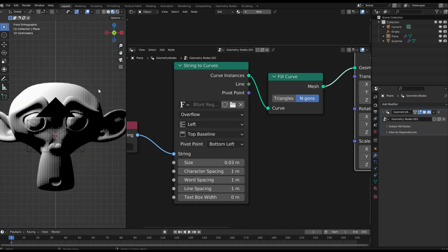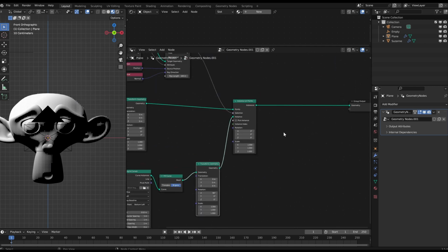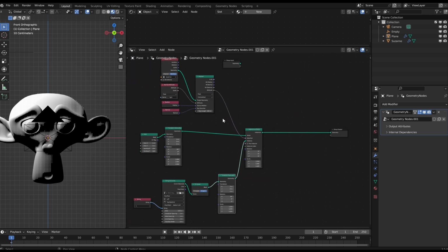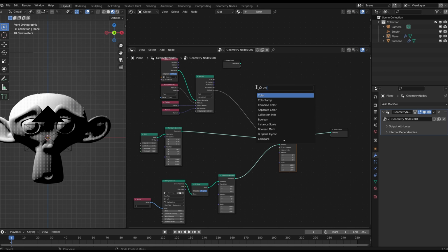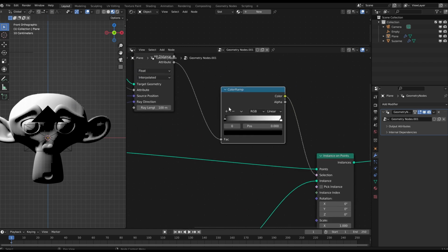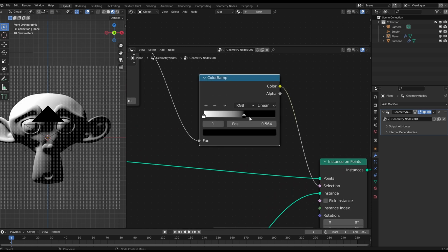And here you can see it displays now the bright areas, which I don't want. I want the dark areas. And for that, I have to do a little arrangement here. Because currently my selection only displays basically numbers which aren't 0. I want to cut that here or put something in between, which is a color ramp. And here I want to tell which part of the spectrum I want to display. And I want to display the dark areas.